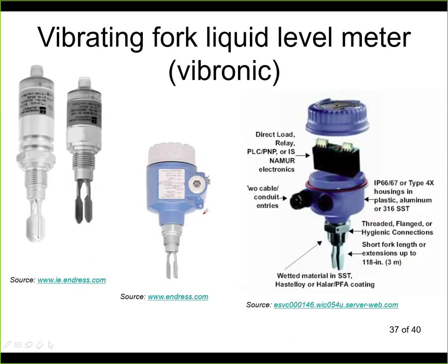Here are a few examples. Here is the vibrating fork itself, which is typically stainless steel. This vibrates like this, and this vibrates like that, very small vibrations. Typically in this part there is a stack of piezoelectric crystals stacked like this on top, and the vibrating fork is in there, and here there is a diaphragm.